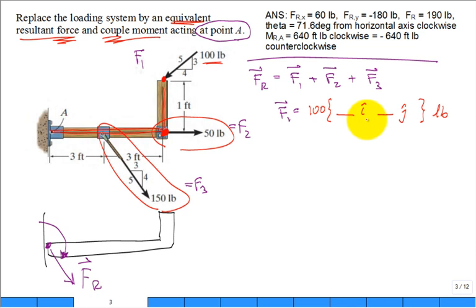What I was looking for is not only a 4/5 right here in the I, the 4 of the 5, but I was looking for that sign, because in our traditional X, Y coordinate system, I didn't emphasize it, but often that's the way we run it, and it's in the negative X, isn't it? And we don't want to forget that negative sign. It'll make a big difference. As well as we have 3/5 coming down, and so isn't there two negative signs? There's two. It'll be negative 80 in the I and negative 60 in the J. Pounds.